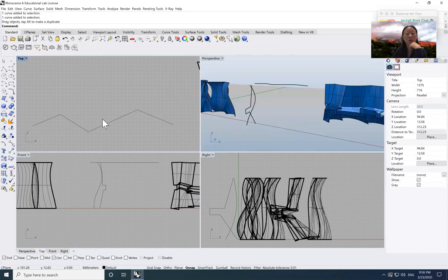Okay, maybe if they line up, they would somehow work. Let me create an arc, use 2-point, start and end and direction. Radius, I think this one is good. So I'll use this and create an arc, drag.